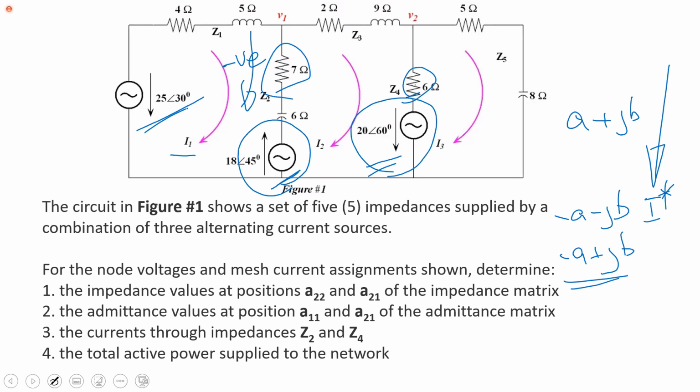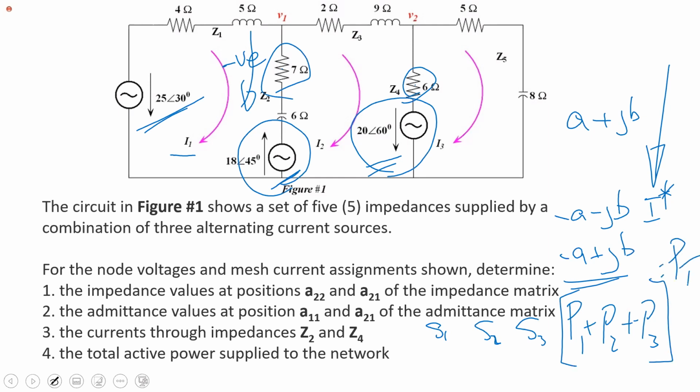And if you have the time and you want to confirm, then you would multiply the modulus of the currents through each branch by the corresponding resistance, and add them. Both should be equal. So you would have gotten S, the powers rather, for the sources. You'd simply add the active parts, and that would give you your PT. Yep, and that's it for question 1.